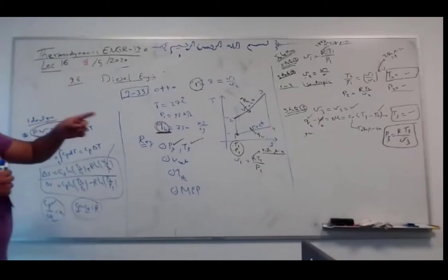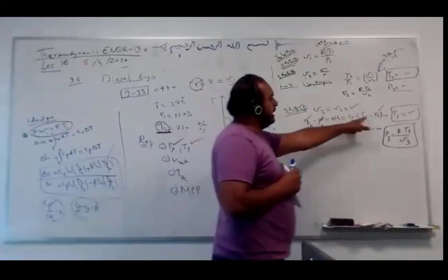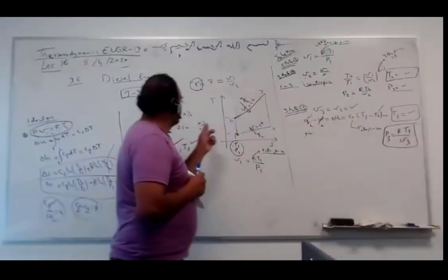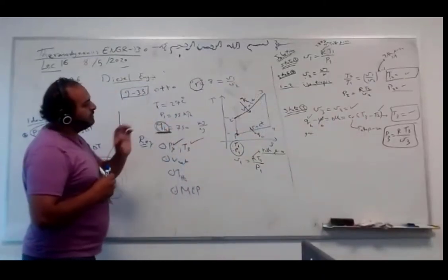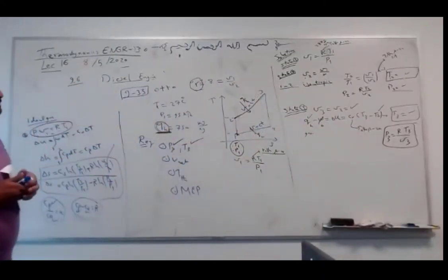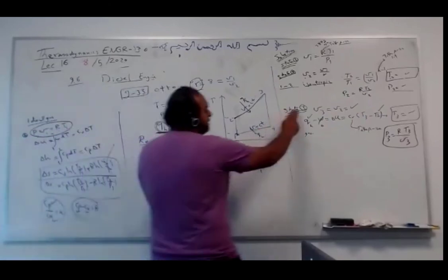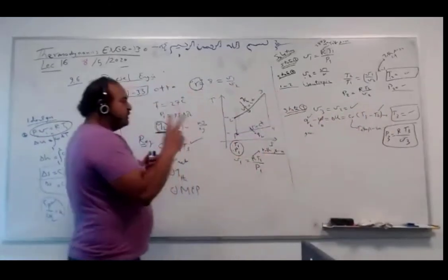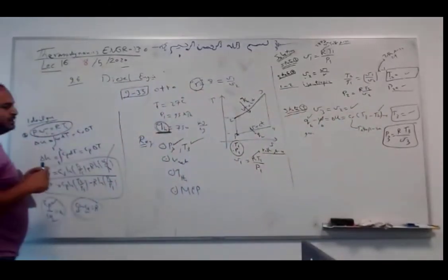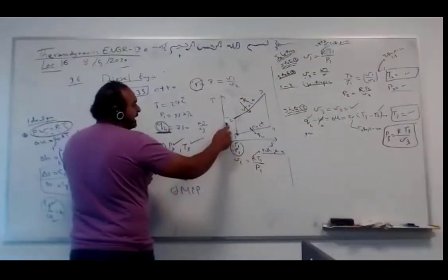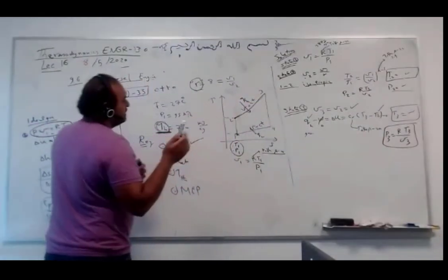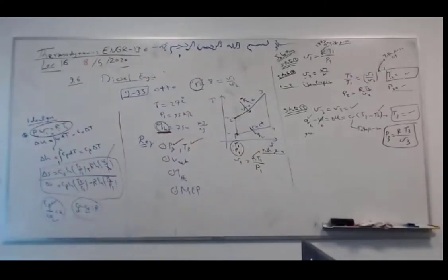Sometimes I give temperature T3. So if you have T3, substitute here, you get Q high. So I can give you Q high or T3 or P3. For example, V3 and P3, you can get T3 and so on. If you have two independent properties, I can get 2, I get something in 3, but I don't know the rest. So he gave me something else, which is Q high.